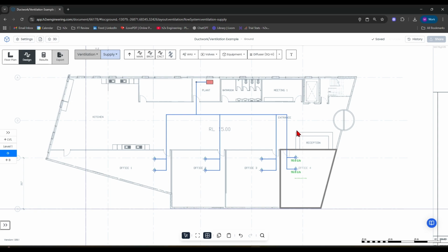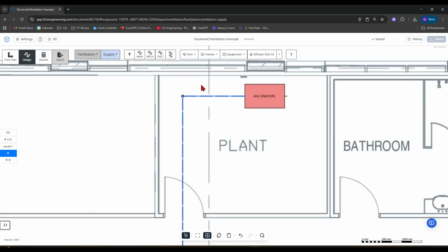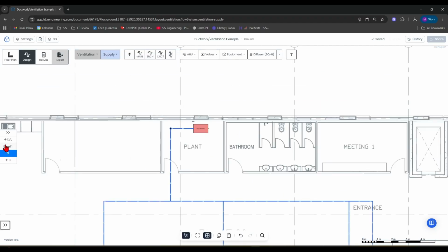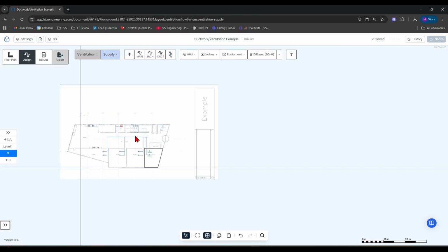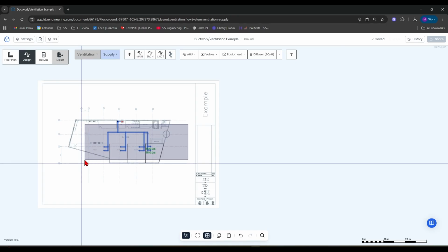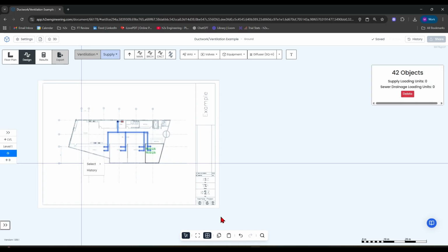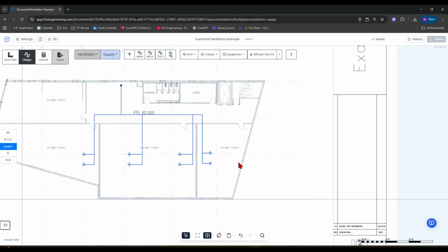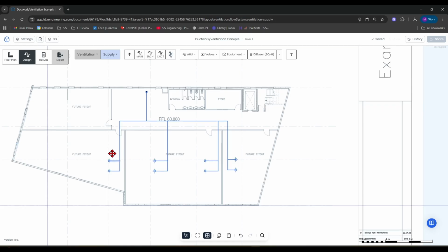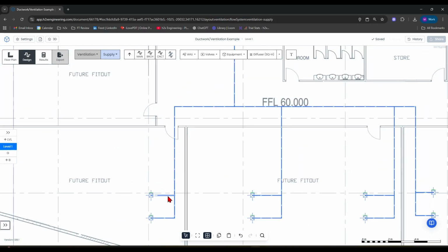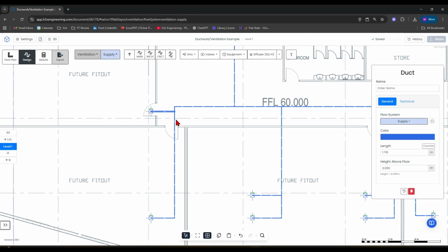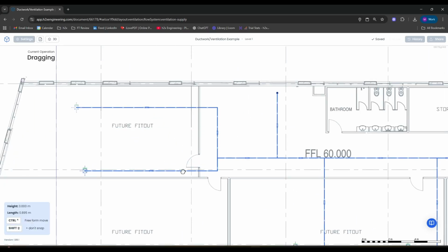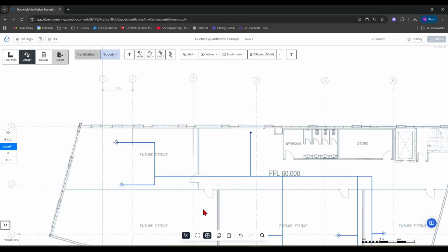If you want to copy this entire arrangement between floors, firstly, you can add a riser, which will allow us to connect another ducted system design on our first floor. If we go to the ground floor, do a right click and select all of our ducts on this level, hit copy, go to level 1, hit paste, where we will then be able to reconfigure our duct design and make it suit the new arrangement. I'm doing this by left click and dragging each individual duct.